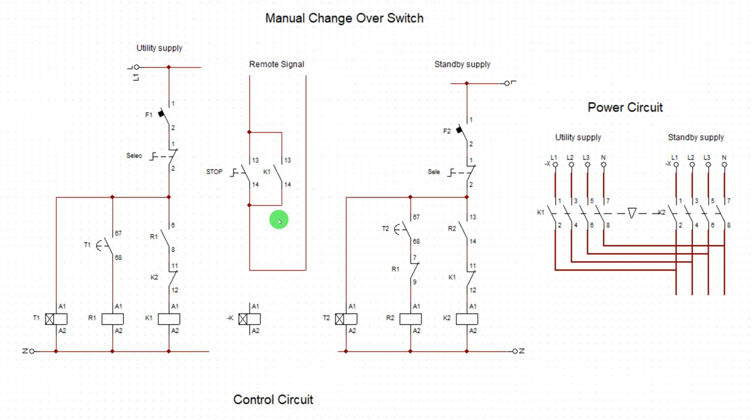So where do we insert that? We are going to insert the timer relay on the mains side so that the mains will activate the timer to shut this one down. Remember that I told you that every timer will be interfaced with a relay. So in that case, we're going to insert a timer and also insert another relay for just shutting down of this. All right, let's do that now.